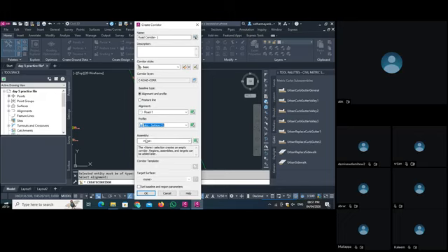Okay. Now we have the assembly, and we gave it the name assembly number 1. So I select that assembly. Then, if different companies have their own template, you can select the template from here. If there is no template, it is not an issue. Target surface: we have to set the target where I want to put my corridor. So we set the target ABC as our surface name, and we click here on set baseline and region parameters. Take all these things properly. If you want to confirm this, then go and click OK here.